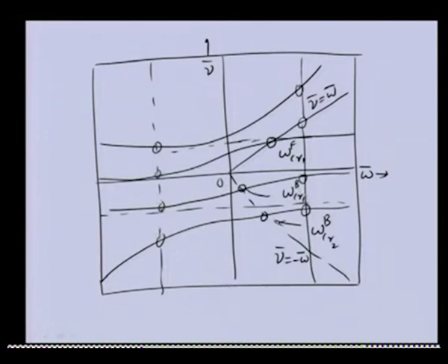And in this particular case, this is called the Campbell diagram. This is a very famous diagram for obtaining the critical speed of the rotor system, in which we plot the whirl frequency with the spin speed. What is the whirl frequency variation with respect to the spin speed?